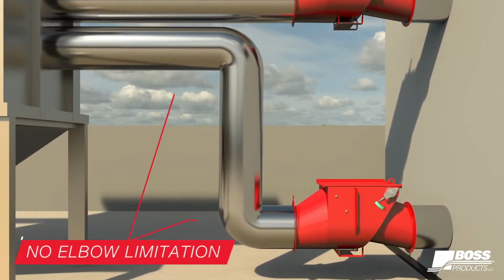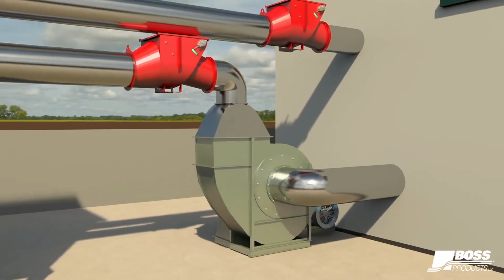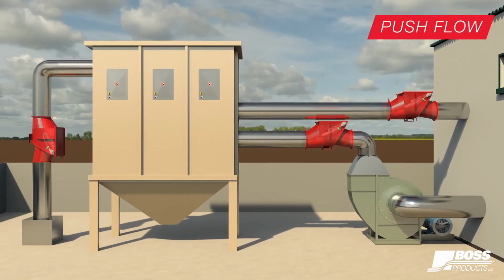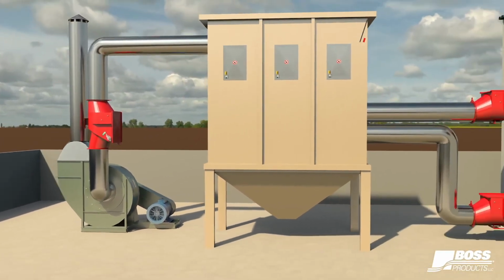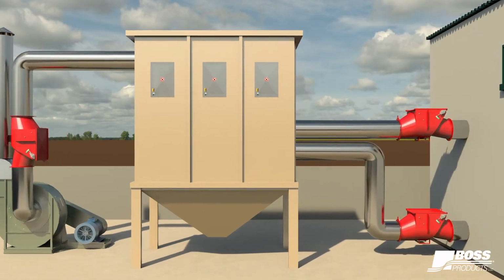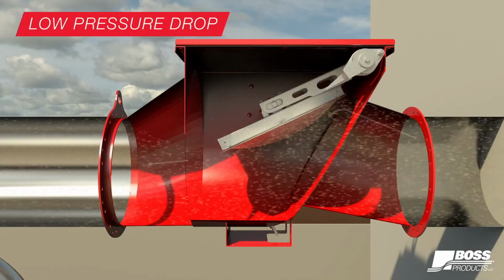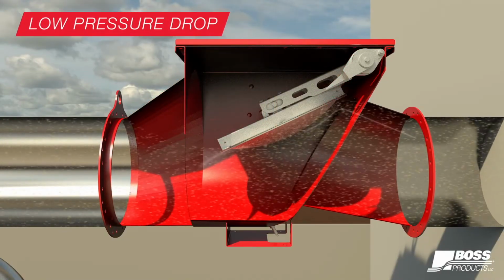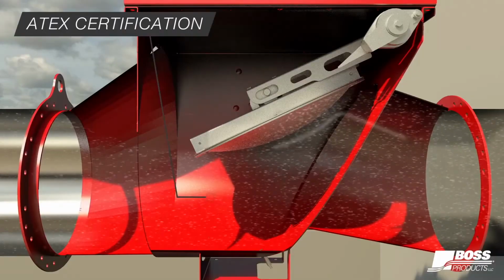There's a position indicator on these flap valves to let you know if the flap's open or closed. That's that little indication on the side of the valve where you see the green and the red, and then once it shuts, that indication will swing towards the red to let you know that your flap is closed, and there might have been an event, or there may need to be some maintenance with it. These are ATEX certified.